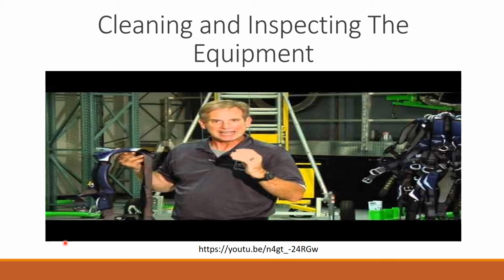Also, cleaning your equipment. It doesn't go so much for the iron, the metal equipment like the tripods and the winches, but this goes more for body harnesses and lanyards. You use a light soap, no Clorox, no bleach, just a light soap and water to clean your equipment and hang to dry. That's the most important part. You hang to dry so the water doesn't sit on there and produce mold.